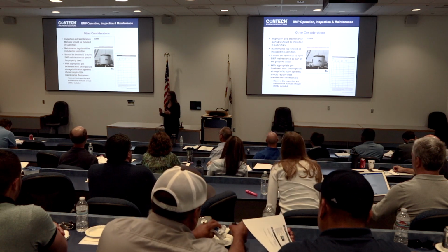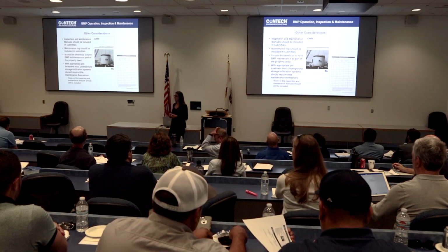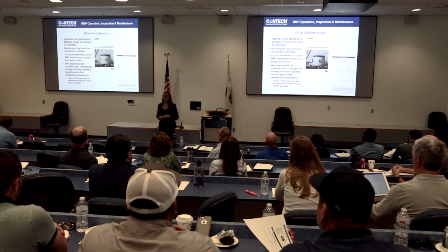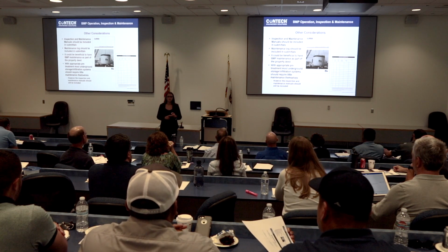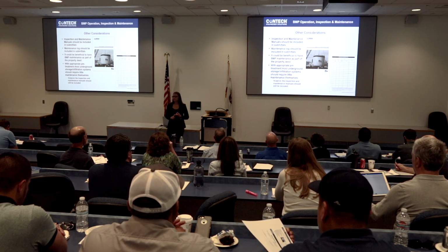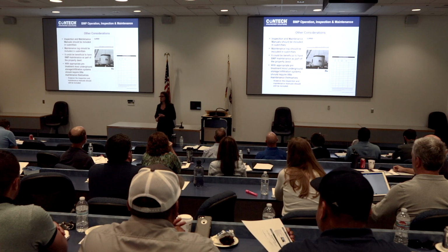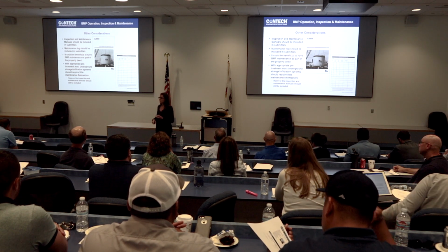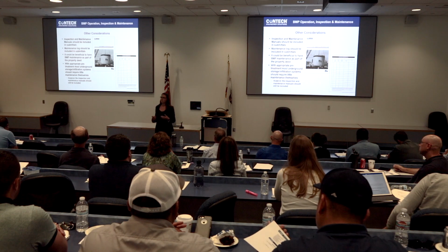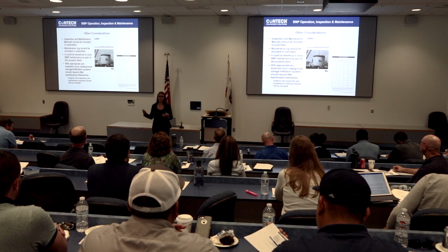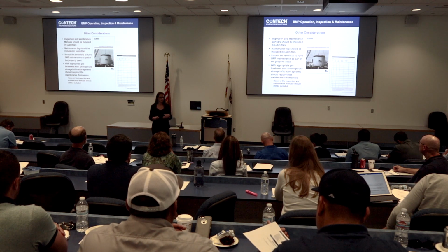So some concluding thoughts I wanted to leave you with is that inspection and maintenance manuals should be included in your submittals along with a maintenance log. These should be provided by the manufacturers. Also, it would be extremely beneficial to your project if you had BMP maintenance included in the original property deed. This ensures the longevity of your system and provides that extra safety measure that these are going to be maintained in the future.